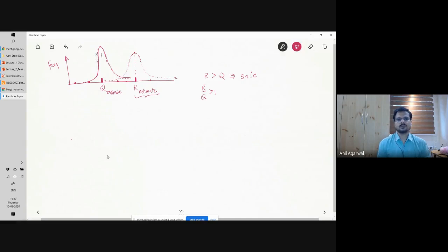So this plot, for example, since I was talking about dead load, I have given a higher peak or a more narrow band, because dead loads are very easy to calculate and we have good enough confidence because we know the density very well, we know geometries very well, so we can calculate these loads very accurately. If it were a wind load or earthquake load, the distribution would have been much wider, shallower and wider. But since this is dead load, we know accurately enough. I'm marking it as sharper.